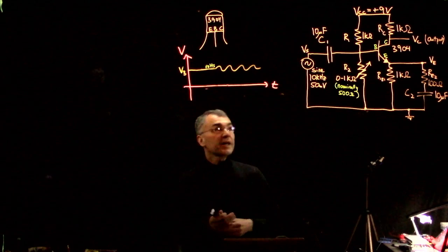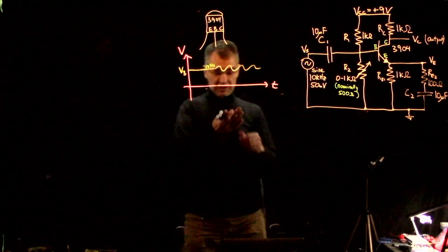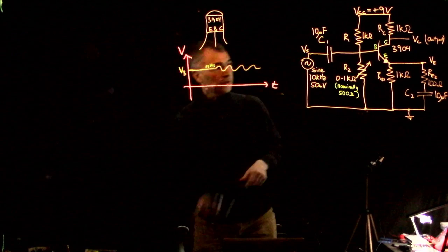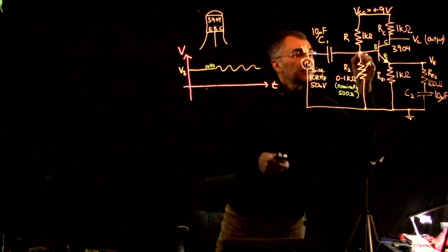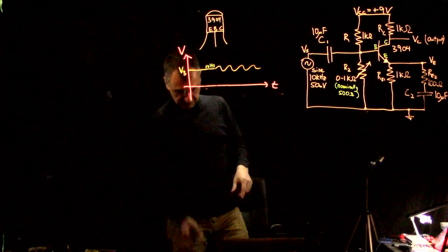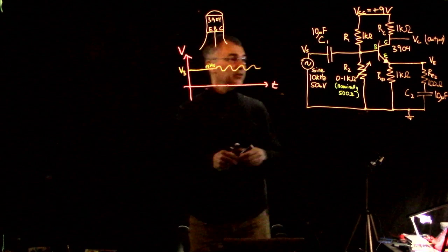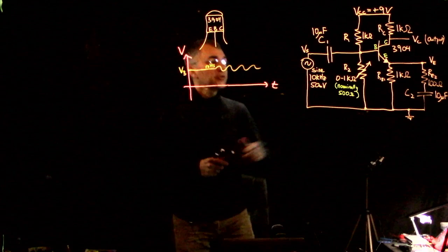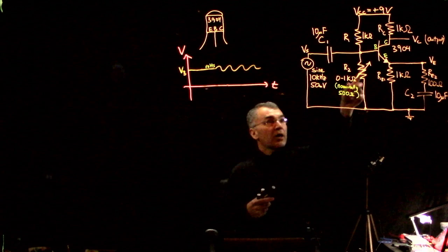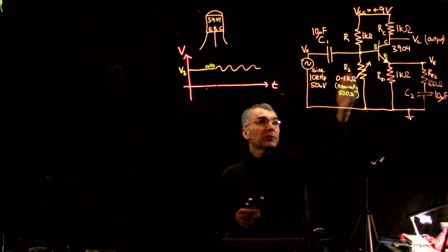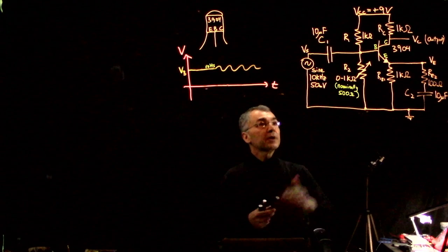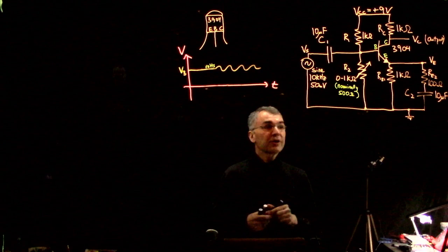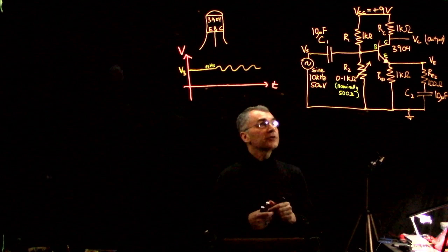So let's look at what happens in this amplifier circuit at DC, when there is no AC signal. We said we were going to set R1 nominally to 500 ohms. It's a potentiometer that can go between 0 and a kilo ohm, but we're just going to leave it nominally at 500 ohms, and then we can see later the effect of tweaking its value.